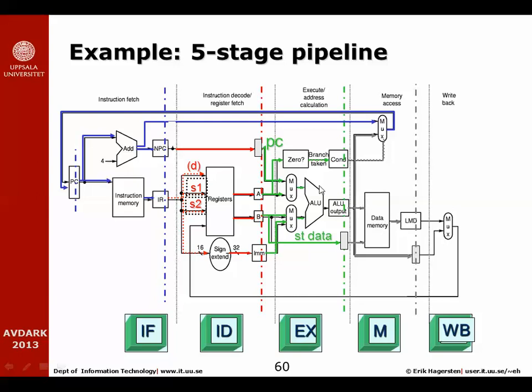If it was just a normal register to register operation with two register values or a register immediate value producing some kind of result, that result will simply go along this path here and will be latched at this point. And if the output was the next address from which we should fetch the next instruction, so this is a conditional branch instruction, that value is now sent to this mux here, and depending on these condition bits, we can choose to either take the purple input or the gray input when we would like to update the PC pointing to the next instruction to be executed.